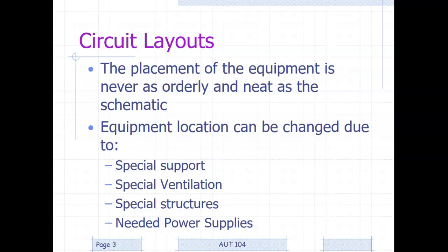You might have to beef up the floor enough to hold it. That goes back to being able to read concrete schematics and know the thickness the concrete needs to be and the interior structure that concrete needs to be. If I've got to hold up a 2-ton robot without my floor cracking, then I might need to reinforce that concrete some more. It happens.